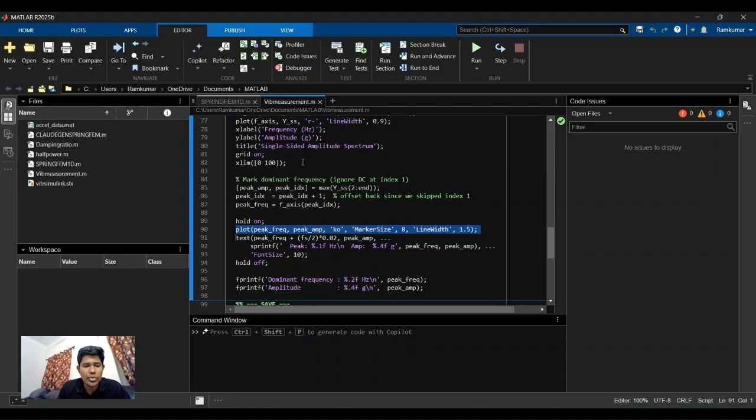So this one forms the analytical core, the fast Fourier transform. The FFT decomposes our time domain signal into its frequency components. So this will answer the question: which frequency carries the most vibrational energy? Before computing the FFT, we apply the Hanning window. So this is essential.